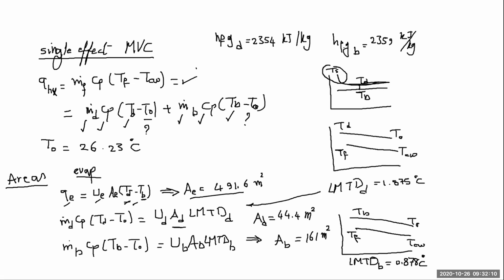So actually, I was going to tell you now, there's something that I want you to do as an exercise: calculate the value of alpha. How much of the fraction of the feed water will go to this heat exchanger and how much will go to that heat exchanger. How can you do that? Who can tell me? I can write here a third equation for the balance that takes care of heating the seawater.